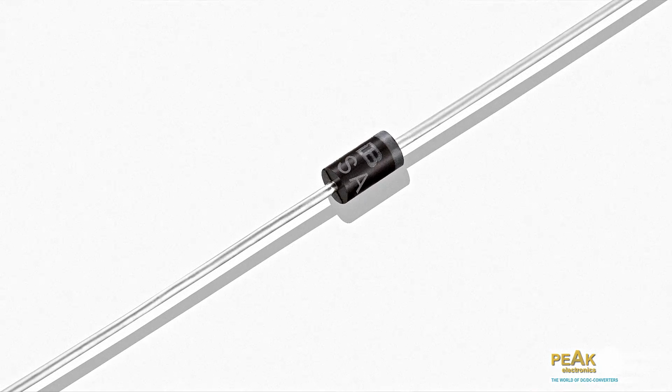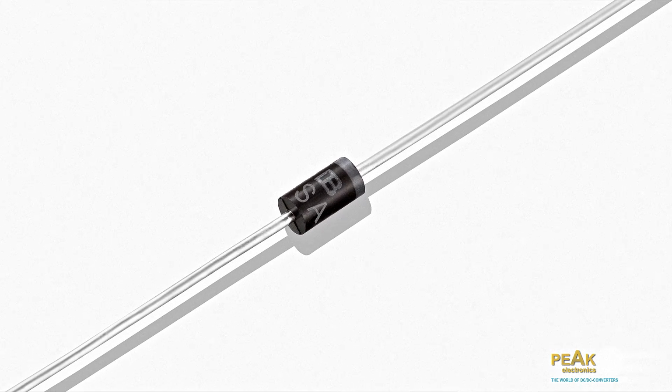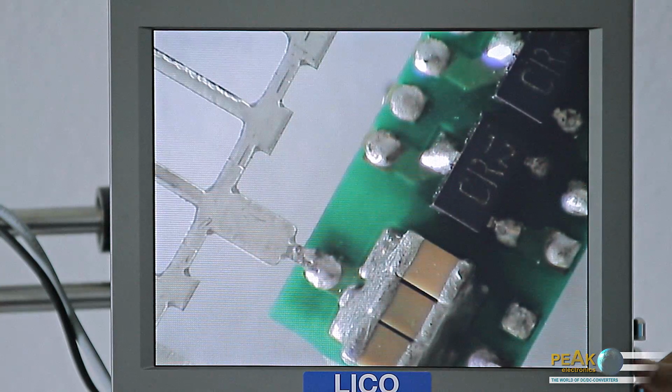Ideally, the input voltage range of the converter is chosen in such a manner that the voltage value of the Zener diode is within its permitted operating voltage range. TVS diodes, for example the 1.5 KE series, can effectively limit greater than 1000 watts, 1 kilowatt, in the microsecond range. The use of a unipolar TVS diode is recommended with DC-DC converters.